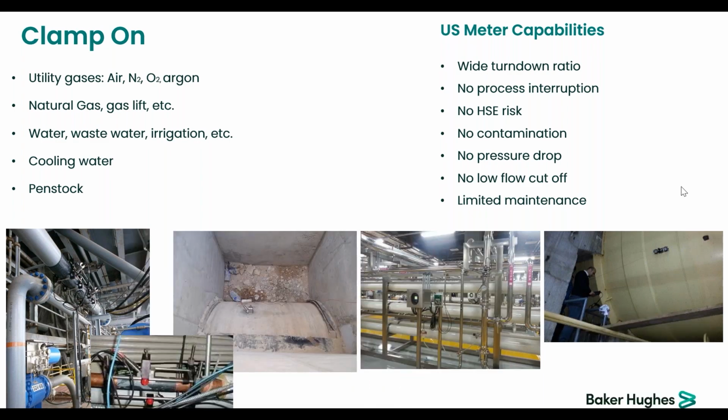Okay, so on that one, in fact, you have a very large path length, very long path length. So you will have a lot of attenuation there, because what I forgot to mention, the reason for the others to struggle a bit, is that you are very close to a gate valve, very, very close. And even if the valve is fully open, there's a bit of disturbance there. And our guess, because we could see that there was a bit of noise for the signal.